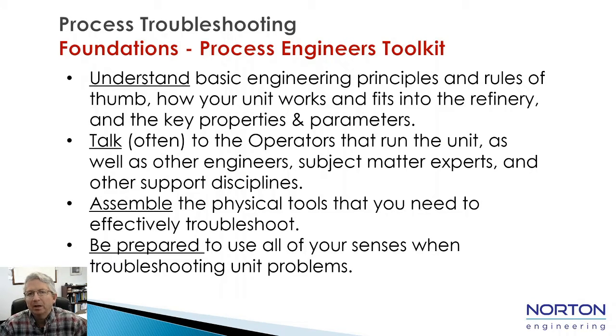You need to make sure you talk often to the operators that are running the unit, as well as other engineers, subject matter experts, and other support disciplines. It's also important that you actually have physical tools that you need so that you can effectively troubleshoot. Things like pressure gauges, temperature guns are all important to have. And you also want to make sure that you're prepared to use all of your senses when you're troubleshooting unit problems.